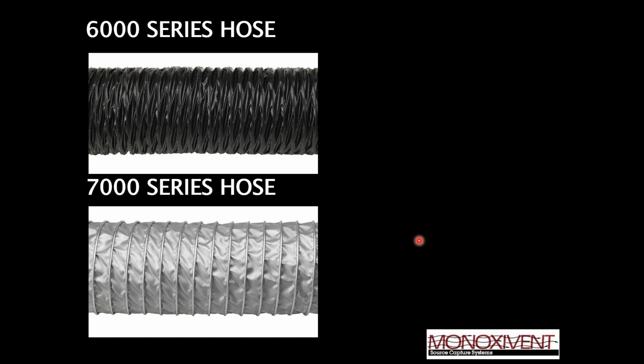There's a ceramic filter that filters the exhaust a second time, and in the process the filter begins to fill up. In order to clean that filter, you ignite it, which they call regeneration. During that process, you can see temperatures of up to 1700 degrees Fahrenheit.